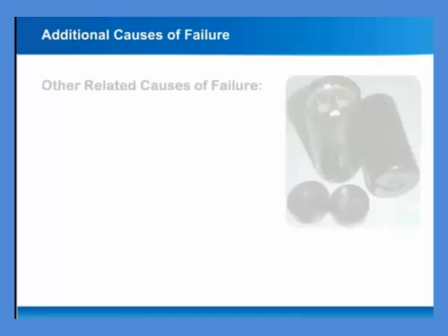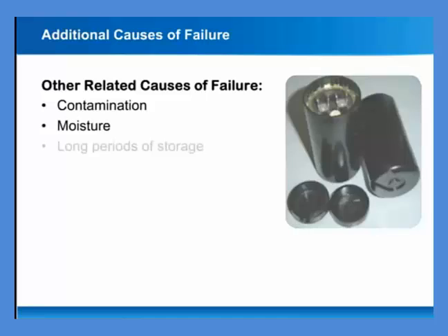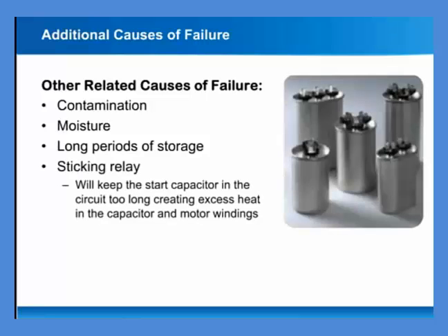There are several other related causes of capacitor failure. Contamination of the materials used in manufacturing will contribute to shortened capacitor life. Moisture and long periods of storage will also negatively impact product life. Using a quality-conscious and dependable supplier will minimize your concerns of defective products.